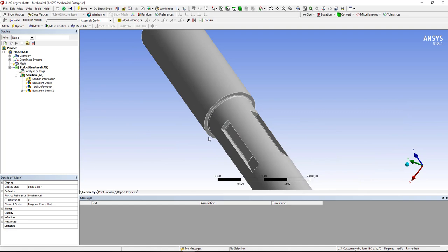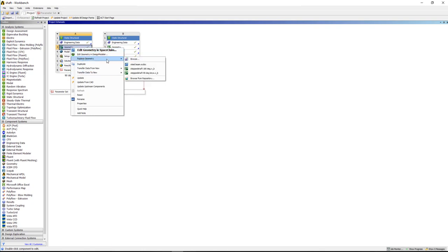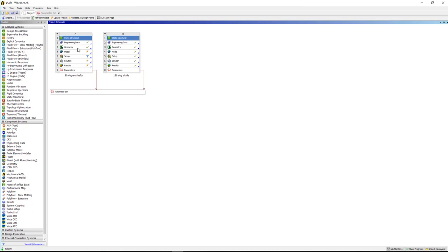This is a chance using FEA to get analysis and to focus on some of the mesh. Now, if we come back to my project screen, I've already done a few steps here. If you right click on a new one, you have an option of importing geometry. I could also replace the geometry here, which would be a similar step. We could go ahead and use a default steel material for this, because we're doing linear elastic analysis, we're comparing two geometries. The specific material properties are not critical to the question we need to answer.